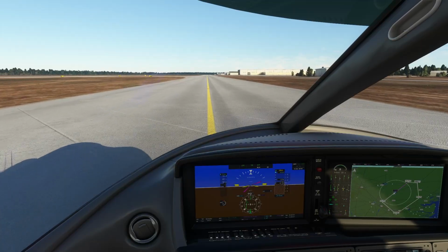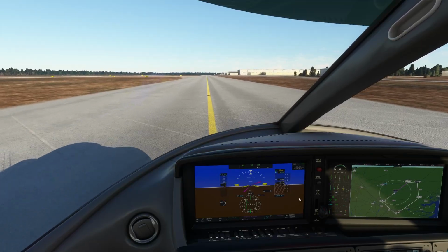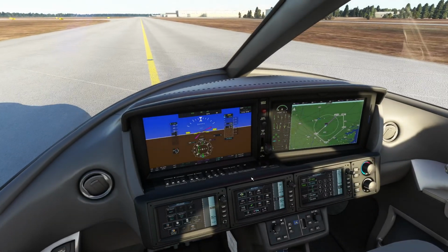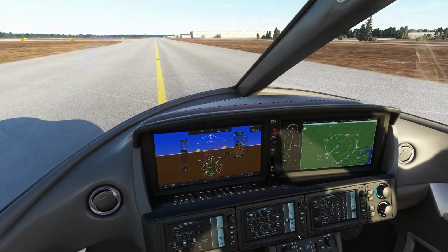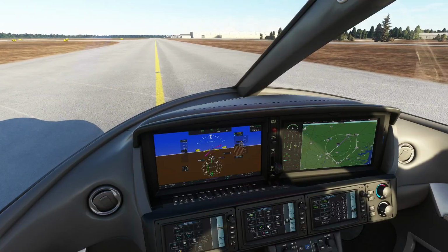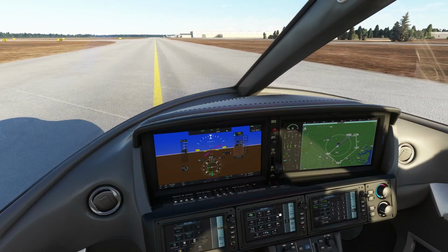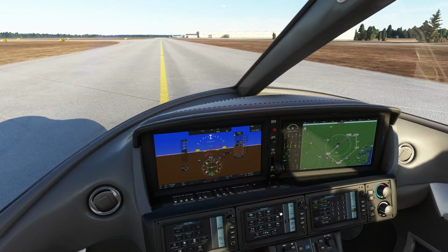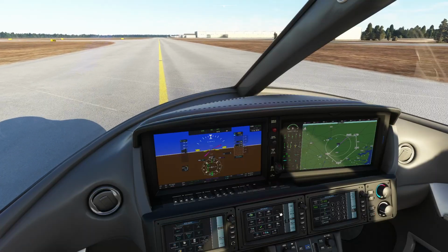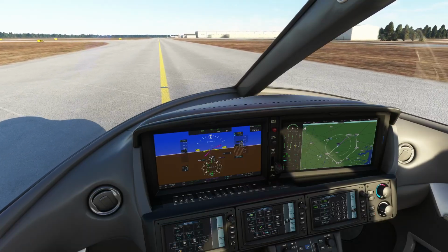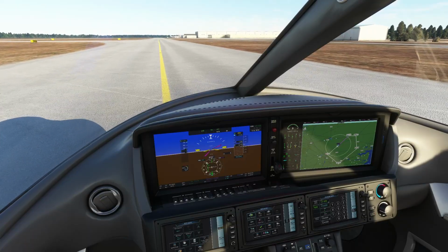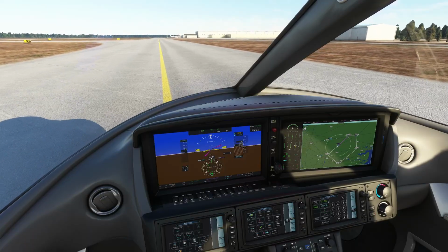Anyway, I'm not going to taxi all the way back. Today was just to show you programming a route and then playing around with the autopilot master control panel to do an approach. Obviously we could have programmed the route using procedures like standard instrument departure, but all they really are is sequences of pre-programmed waypoints. So we looked at programming waypoints by hand. All a SID or a STAR does is program a whole bunch of them for you in one go.